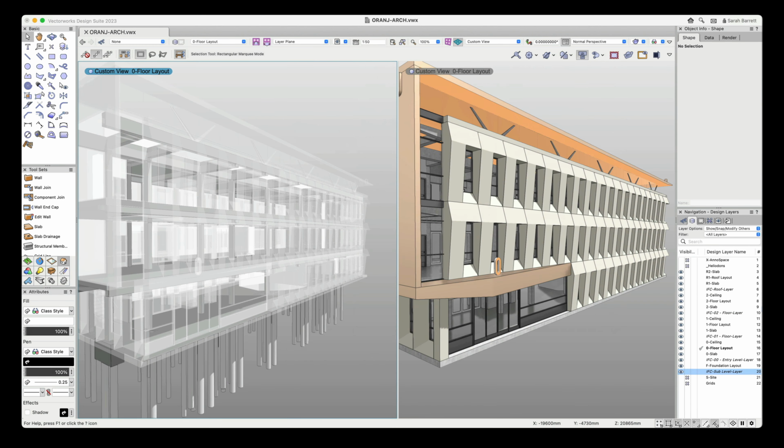Once you have your IFC model, there's a lot you can do with it. But in this scenario, where not everyone is creating an IFC model, it makes sense to simply use it for reference and for coordination meetings. You can send your IFC model to your structural engineer. They can link to the IFC in Revit, and then you can have your architectural model within their file for reference purposes. You can do the same with their IFC model by referencing it into your own file.